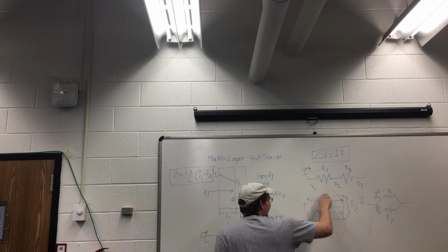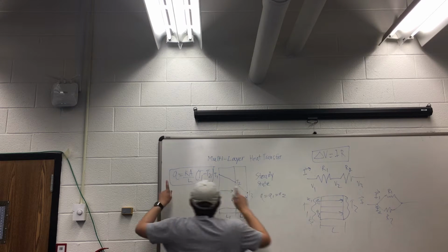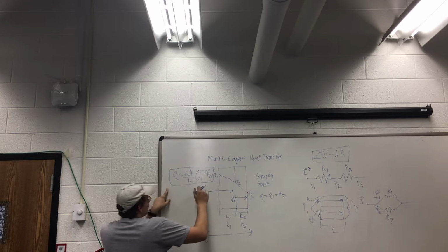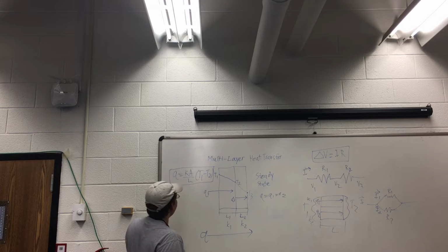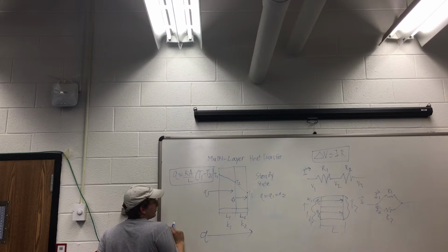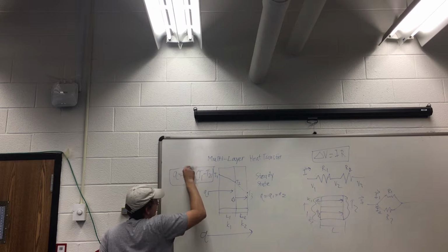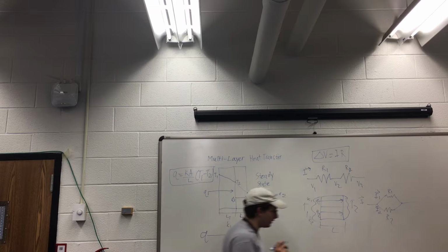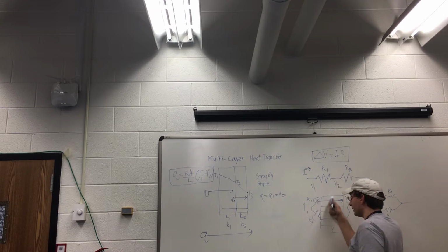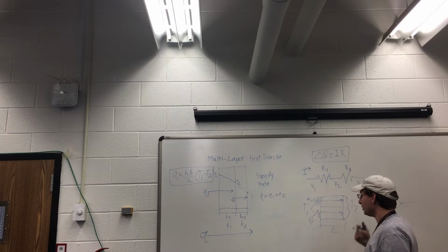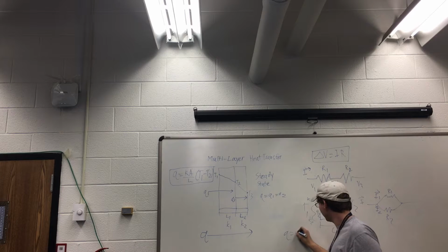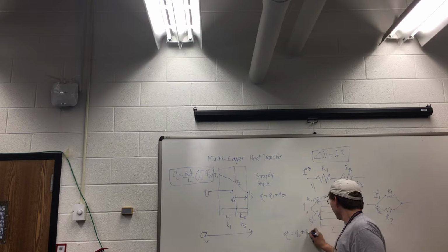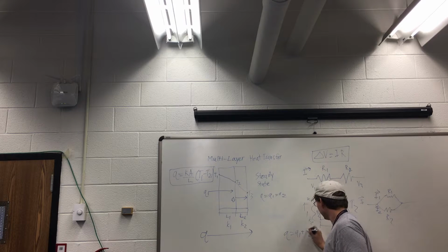Okay, so if we look at this equation we have, they have the same temperature drop, the same area, and the same length. The only thing they don't have is the same thermal conductivity, meaning that these two cannot be the same value. So what we're going to do to find our overall Q is just add them together. I know it's simple, isn't it? Or it just looks simple.